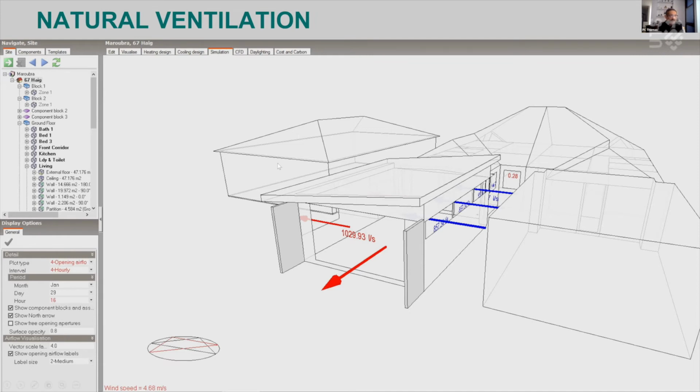Now, in this particular picture, it is actually a little bit interesting, and I wanted to spend a couple of minutes on that. You can see that the airflow is coming in from these higher windows and leaving through the lower windows and from the open sliding door. Now that's not how you normally show natural ventilation happening. Normally, you would draw the arrow from the lower window to the upper window, because you are thinking that all the natural ventilation takes place due to buoyancy flows.